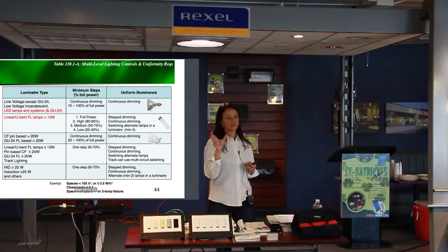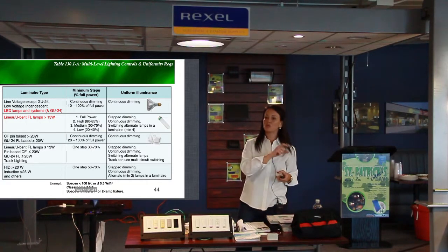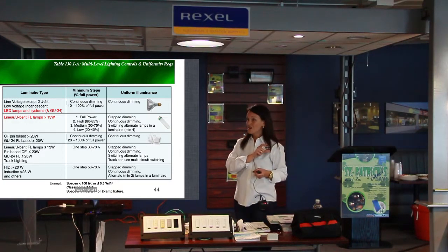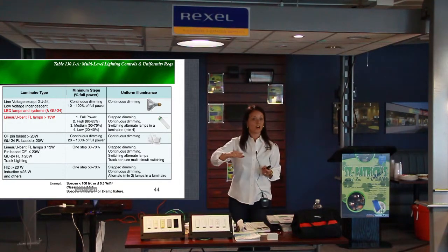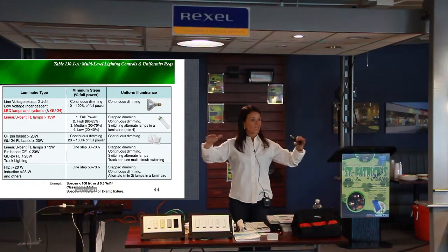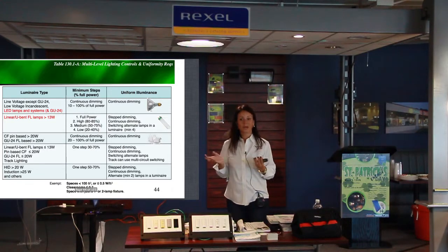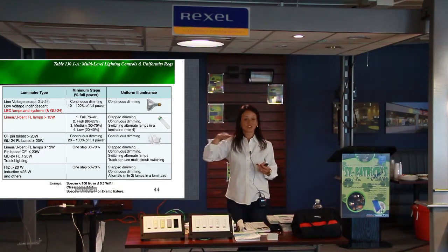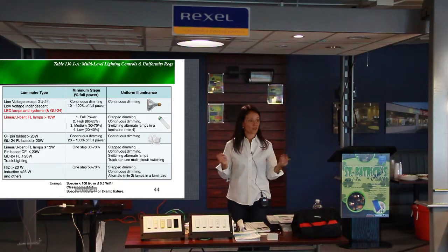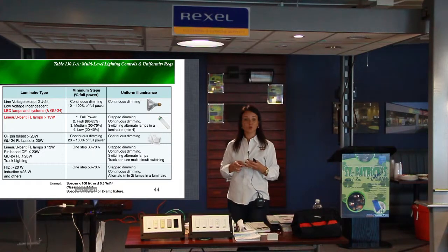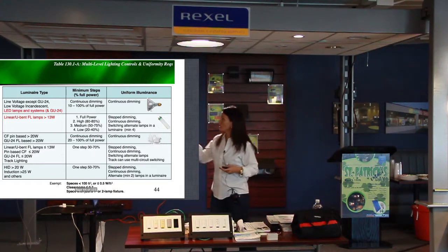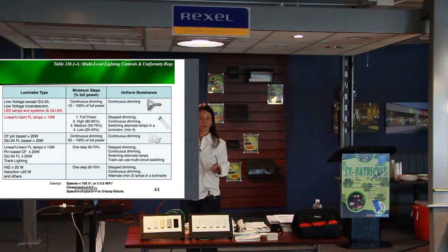And 85% is a number that's directly related to what the demand response controls are talking about, because you need to drop 15% of your total lighting electrical load in that space. Unless you have a fixture with 4 lamps, there's no way to do that. And I don't think we're going to see fixtures with 4 lamps and multiple ballasts in projects moving forward. So that's the big one, because dimming costs a lot of money, right? I mean, are there some fixture reps here in the room?